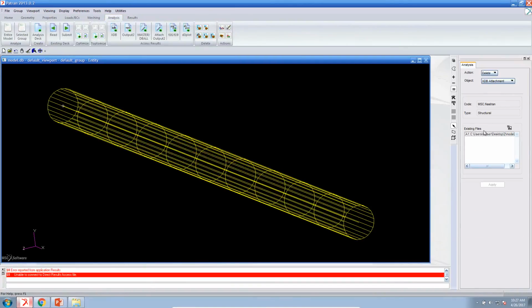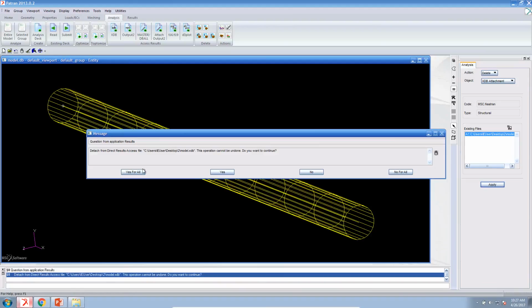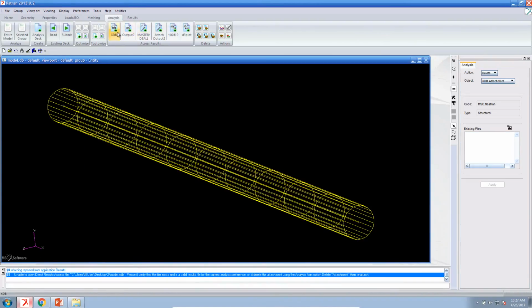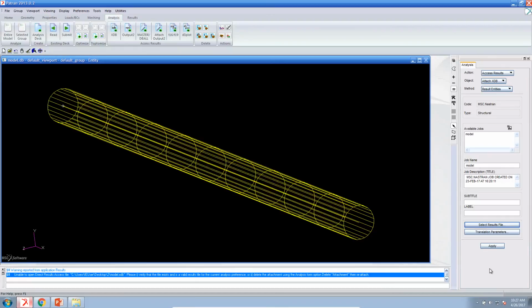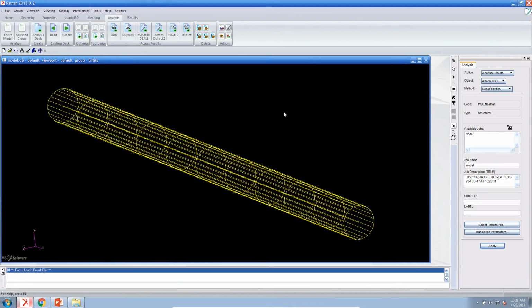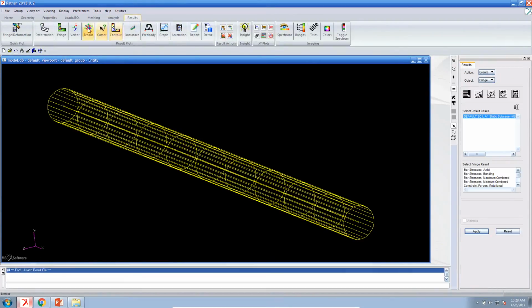One thing you'll notice with optimization, the optimizer will vary some of the dimensions, obviously, and it will do this until it encounters the minimum, or it encounters a design objective that limits the optimization. In this example, what you'll find happen, it will steadily try to reduce the mass of the structure, so it will vary the radius.